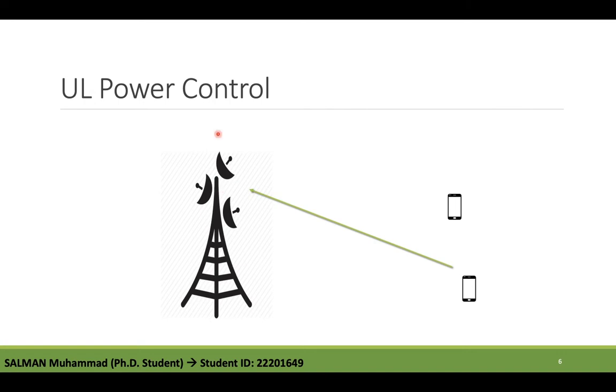Firstly, in general, the decoding performance is not determined by the received signal strength, but rather by the received signal to interference plus noise ratio, which we call SINR. And the appropriate received power thus depends on the reference level at the receiver side, and an interference level that may be different between different deployments, which may also vary in time, as for example, the load of the network varies.